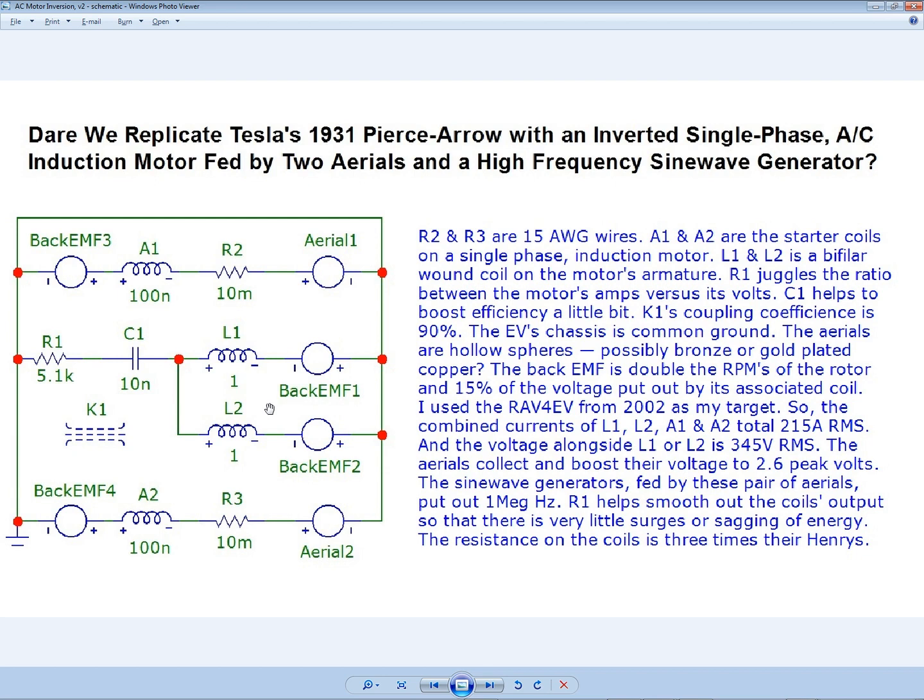I did stumble. The first time I discovered this was when I was designing op-amp circuits in Paul Falstad's simulator, and I discovered an area of negative resistance, and I put a spark gap there, and it improved performance. So if you recognize what areas are negative resistance, you can take advantage of those areas to boost the gain on your circuit, and that's what I've learned here.